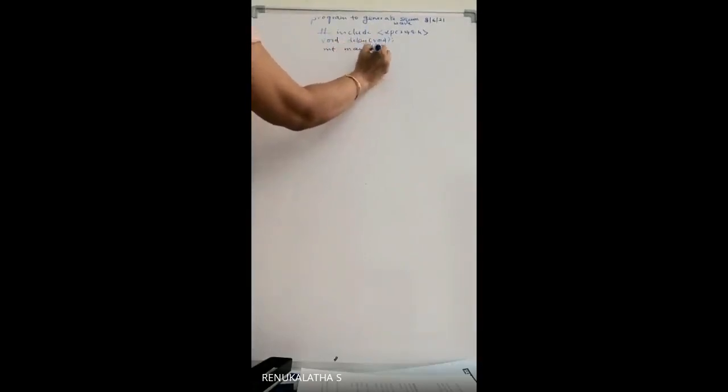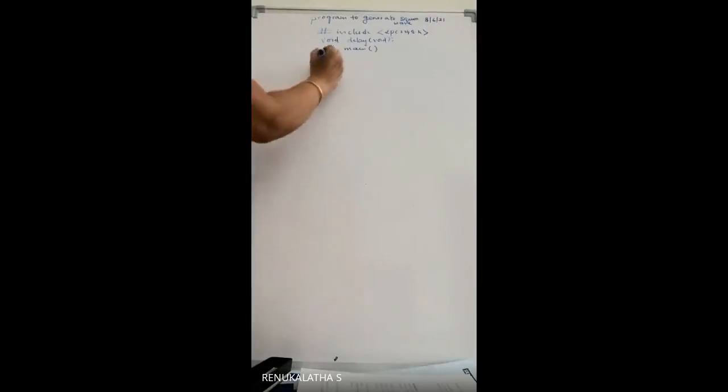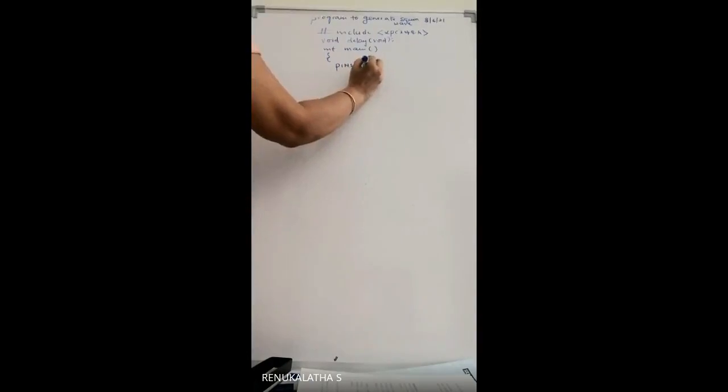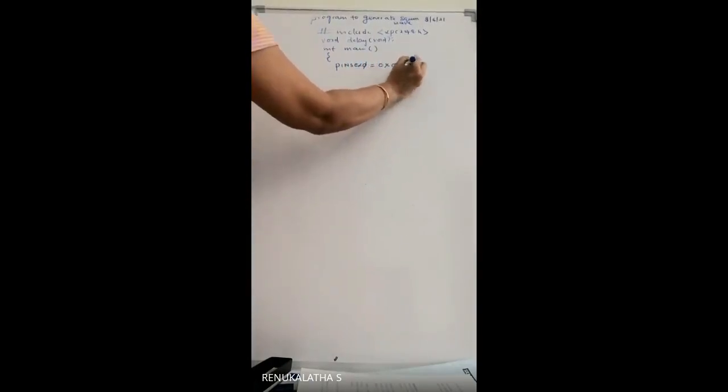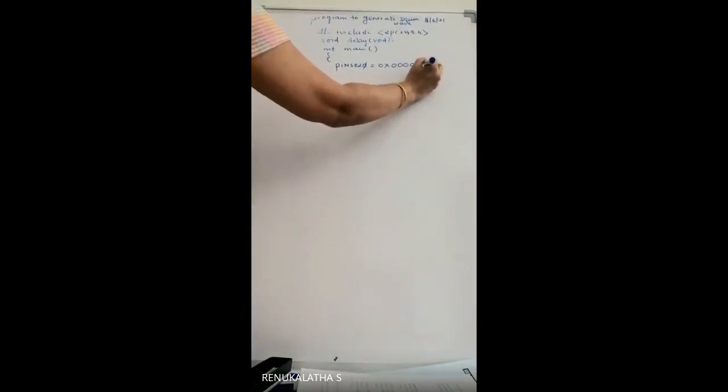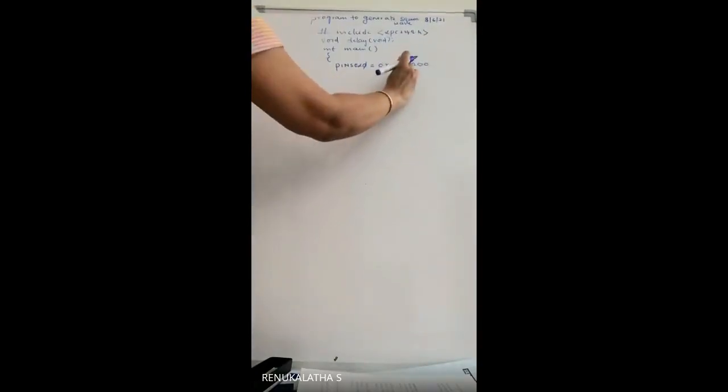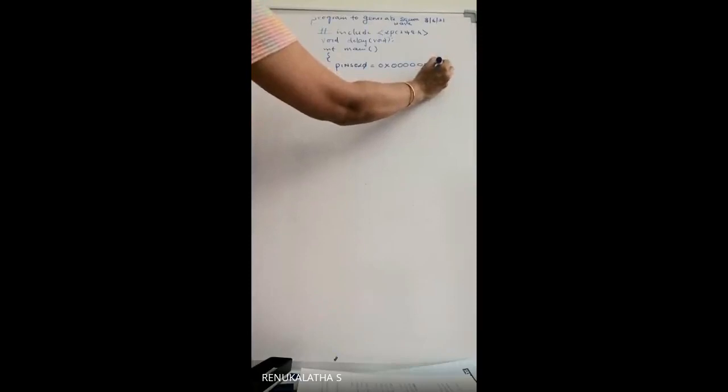And then start the main function. Pin select also we need to do: PINSEL0 is equal to 0, all are GPIO.